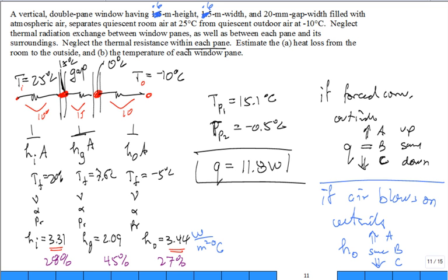All right. So when do we have a low H? Just as not a clicker question. Think about boundary layers. Do you have a thick boundary layer or a thin boundary layer for a low H? Low convection coefficient, you have a thick boundary layer. And so what happens when you start ripping fluid across the surface? You start thinning out that boundary layer. Maybe it becomes turbulent, really rips it up and chews it up and makes a very thin boundary layer. That's going to promote the convection coefficient. H is going to go up as I really blow the air across it.